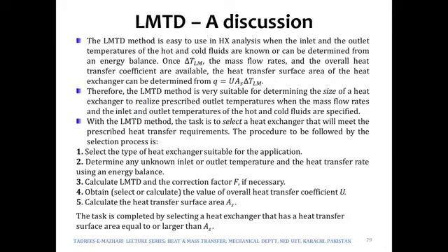So in the end, this is a very useful discussion which has been presented over here. As I had mentioned earlier, since the log mean temperature difference requires its calculation, we must know all the 4 temperatures: hot in, hot out, cold in, cold out.